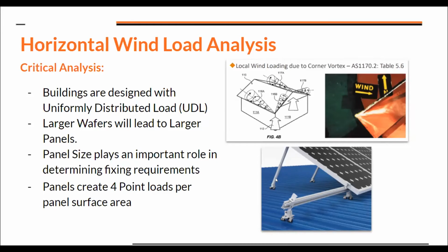Now, as it's doing that, the whole way the building is being forced down and the wind pressures acting on that roof is now completely different to what it was designed for. And although it's really good from an energy point of view that we're getting larger panels and everything like that, and we want to encourage the growth of the industry, we just want to also make sure that everyone understands there are negatives to that as well, which is what it does to the structure.